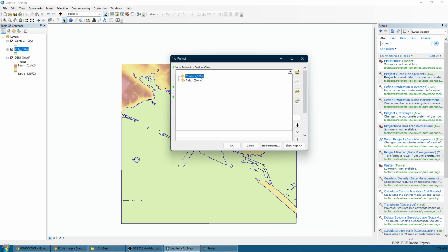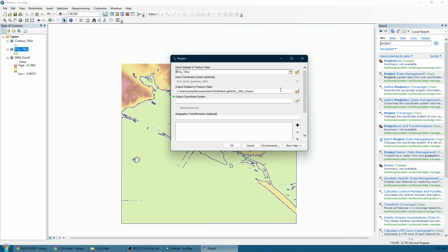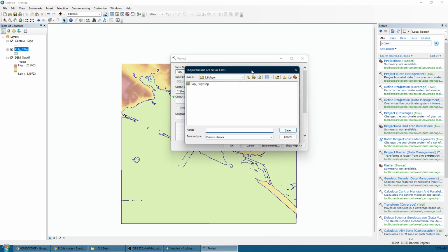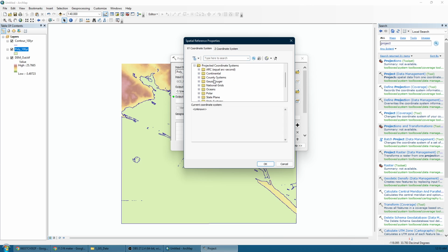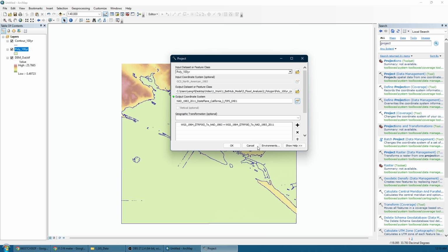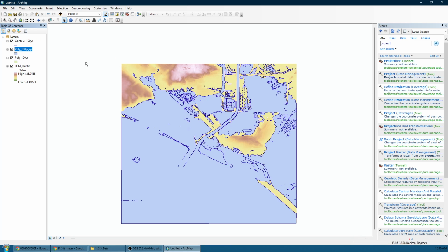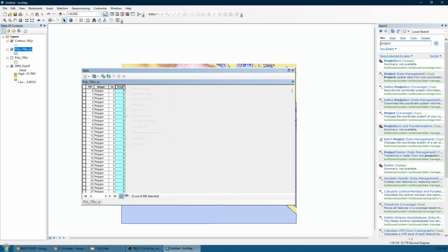Make sure that I don't have this. Change the polygon. Use a projected system, State Plane, in meters, just the one in California. Okay, right now I have one that has the California projection system. Then I can just add a field here, calculate geometry, calculate area here.